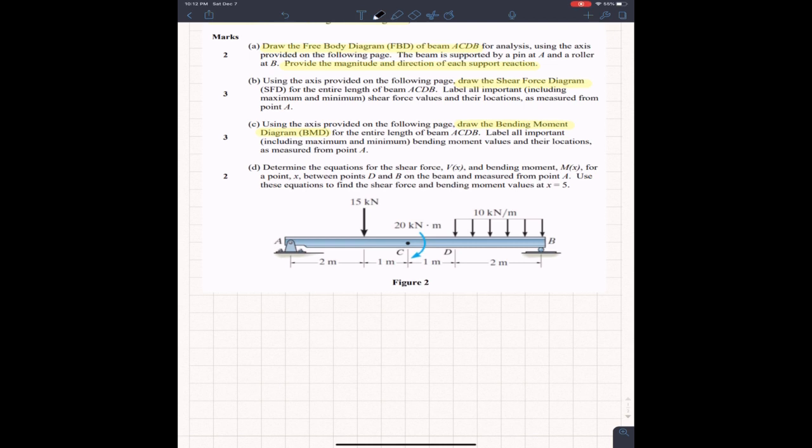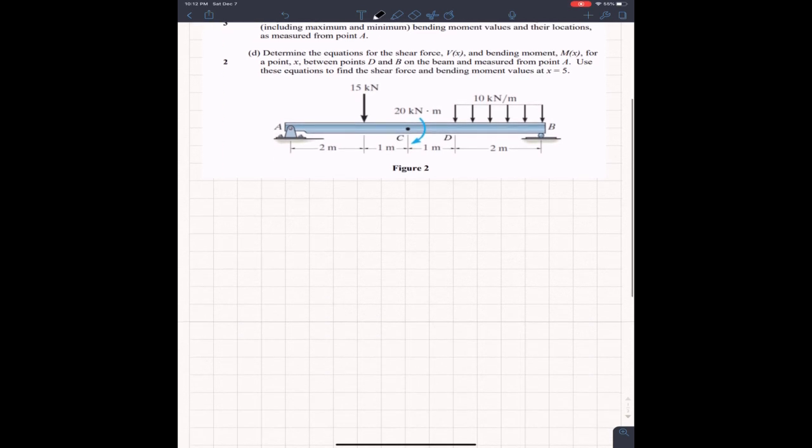So this question is kind of nice because they kind of hold your hand and take you through exactly what they want. So we're going to come down here and we're going to say part A. And the first part is determining those support reactions. And when we determine support reactions, we must always draw a free body diagram. Always. So I'm going to draw just a simple beam like this, coming up, coming across. And that didn't work. I need to draw a rectangle. All right, let's try again. So it doesn't look like a rectangle at all, but Notability helps me out and I'm good to go.